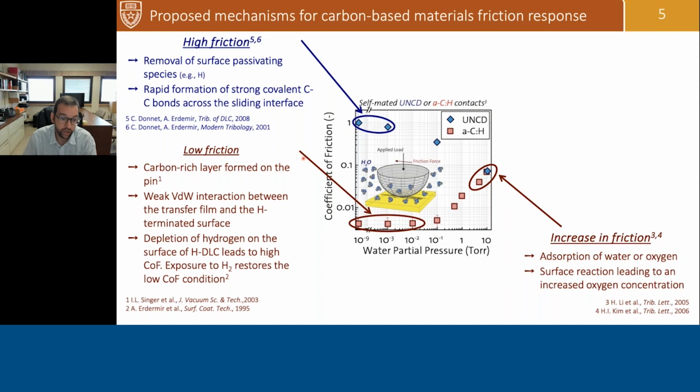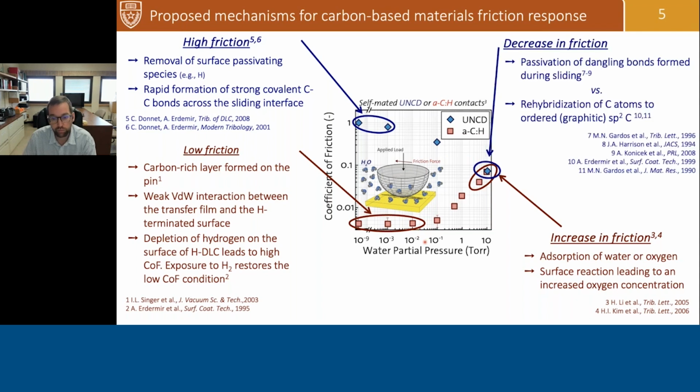environment or low relative humidity values has been shown to be due to the removal of participating species from the film, such as hydrogen, with the subsequent rapid formation of strong covalent carbon-carbon bonds across the sliding interface. And this has been nicely shown by molecular dynamics simulation by Judith Harrison and others in the community. The reduction in coefficient of friction as the water partial pressure increases has been proposed by different people to potentially be due to two completely different mechanisms.